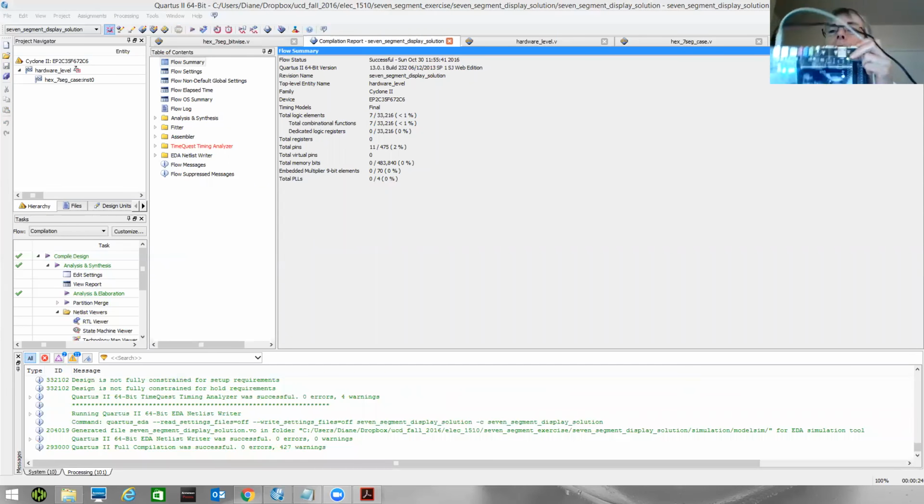All I have is my Altera DE2 board plugged in. You can see that it's just flashing. There's nothing in the memory. Remember, if there's a program in there and you power it off and then back on, since I have it in run mode, not program mode, it loses any program that was previously in there. So I'm going to now go to the programming step.